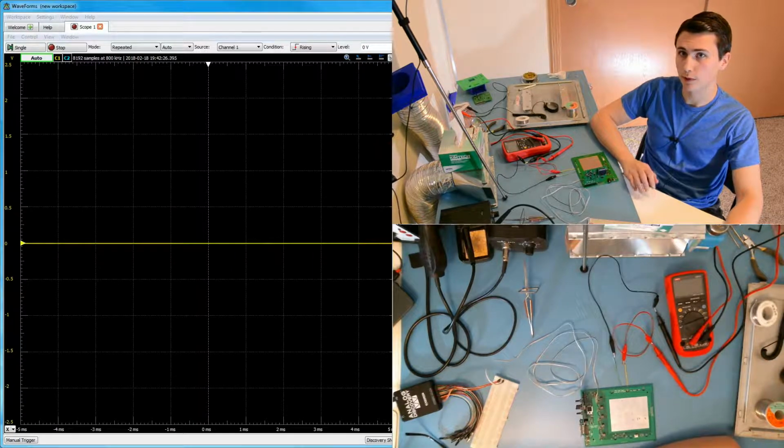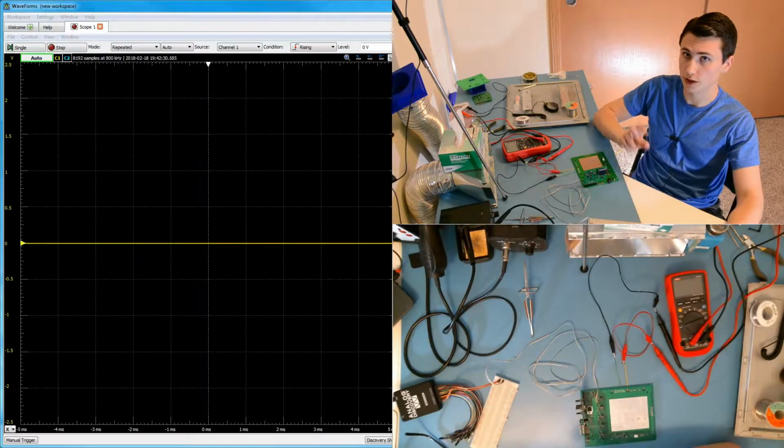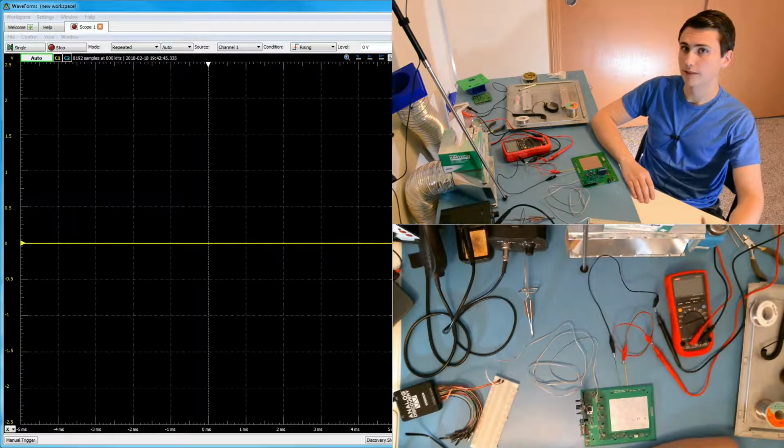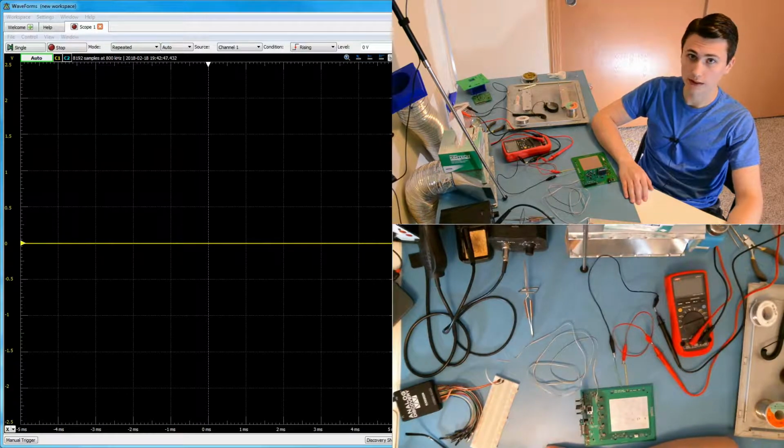When we're measuring this performance, the plant light is modulating each channel from 0 to 100% brightness, which is requesting from 0 to 300 milliamps of current behind the scenes. What's being called 100% brightness is truly 90% of the maximum 333 milliamp output of the LED channel, but we software limited that to 300 milliamps in the actual firmware. So with that in mind, let's gather some data.